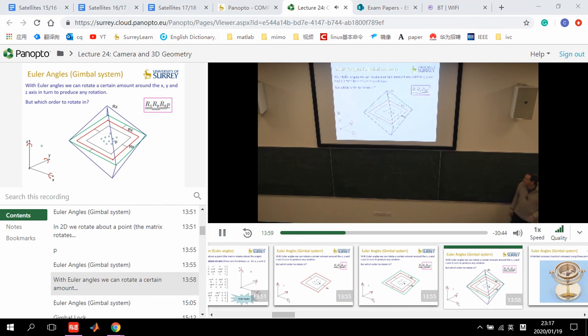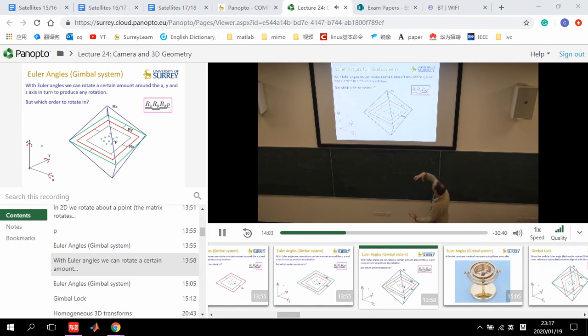And then finally, we're going to add our third axis by imagining yet another metal frame, somehow suspending this green frame such that we can pivot it in this direction, that's orthogonal to the other two directions, and that will allow us to pivot by some Rz amount, some theta that we put into the Rz transformation. And the result of those 3 transformations is our image of our points P prime. Does that make sense?